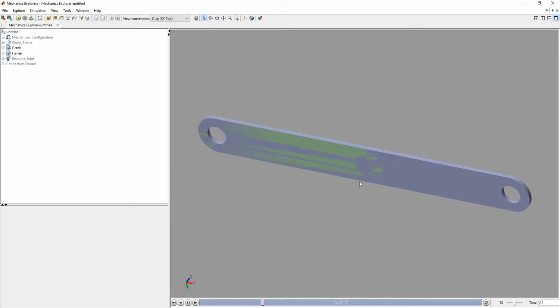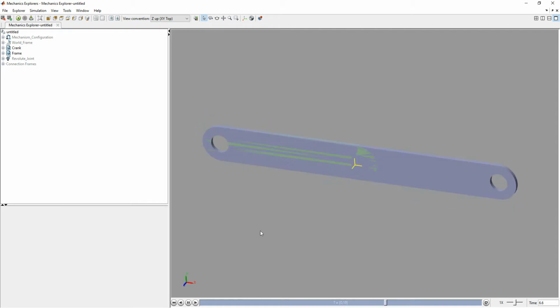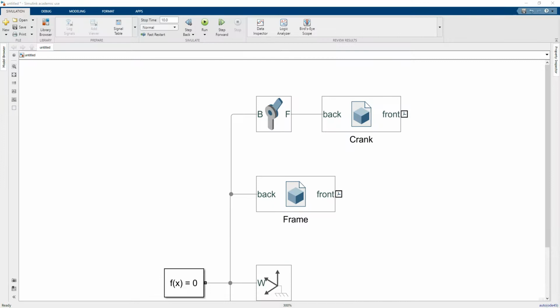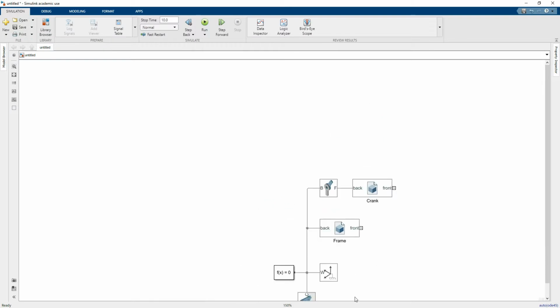Two things we need to visit. First thing is, you'll notice now that it seems to be inside, it's penetrating within it. So what we do know is it needs to be moved on its axis, and technically there is a perfect joint between each component. That tells me that gravity is actually acting against it, so in the Z. So in other words, this is like it's laid on a table, so it wouldn't move. Right, two seconds. First things first, let's get this gravity fixed.